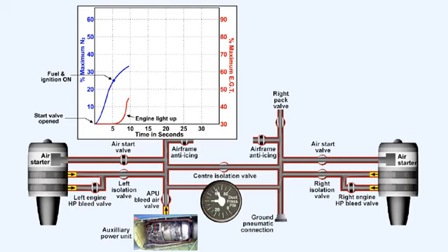The initial increase in EGT is quite sharp, because as combustion does not occur immediately after ignition is selected, there is an initial build-up of fuel in the combustion chamber. Once this fuel does ignite, it tends to overpower the cooling effect of air being fed from the compressor. Once the excess fuel is burnt off, however, and the fuel-air mixture becomes more balanced, the increase in EGT steadies. The gas, which is being produced in the combustion chambers, now adds impetus to the turbine blades, which eases the task of the starter motor, and the engine continues to accelerate.